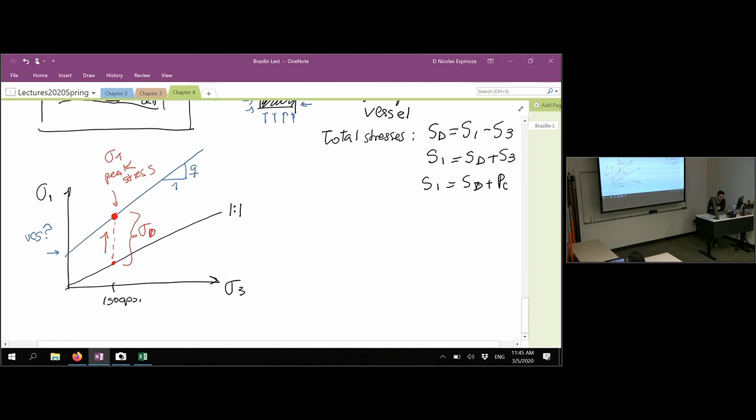So sigma 1 minus initial sigma 1 would be deviatoric stress? Yes, so in all these tests, what we do, and what I'm asking in this particular problem, is we increase the deviatoric stress. Usually it starts at 0 or a value close to 0, and then goes to a maximum. This value is the peak. And that value over there is the same that you use over here.